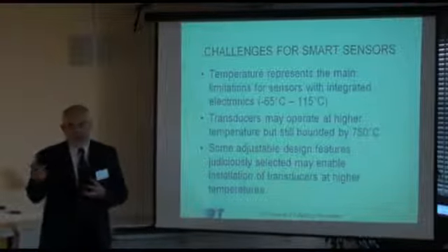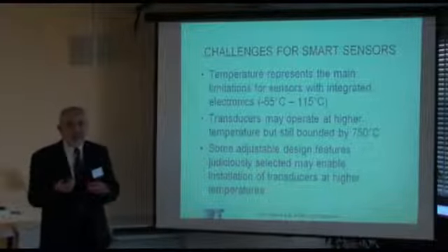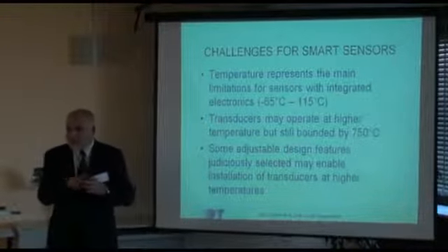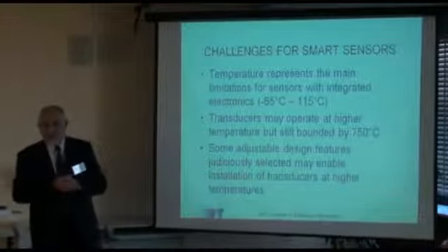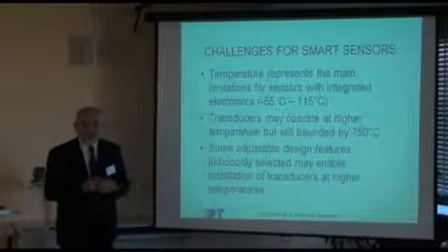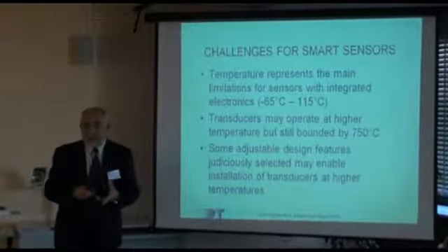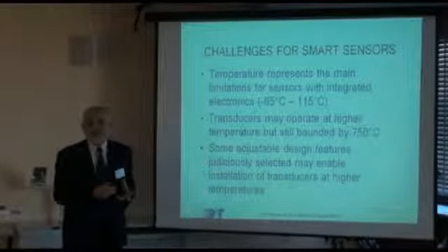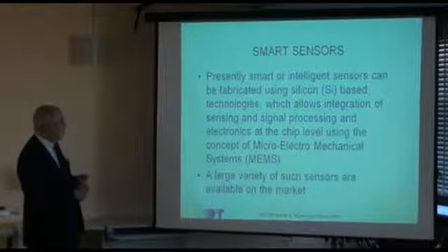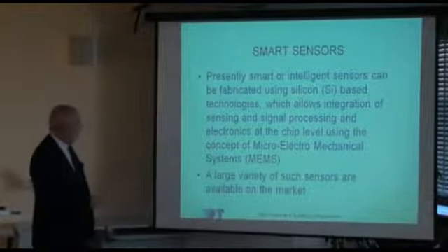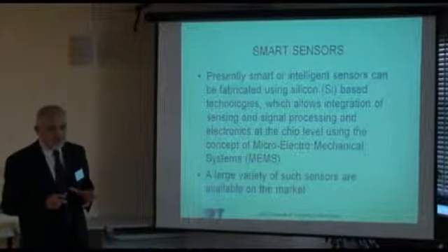Or eventually, in SOI, silicon on insulator, you might have a capability of 250 degrees, and if you judiciously cool it, somehow you could probably tap a 300 degrees zone. If you operate on silicon carbide, we'll discuss that tomorrow, you could go probably even to 500 under the same conditions. But they do not operate at 500. They are not employed to operate at 500 degrees. So at present, all electronics is based on silicon technology.